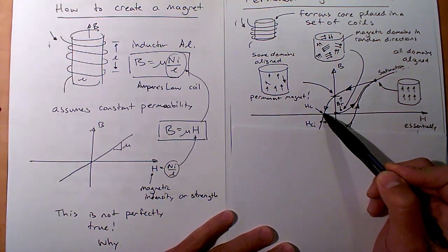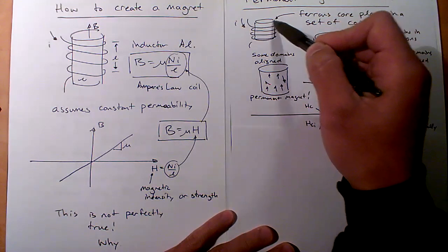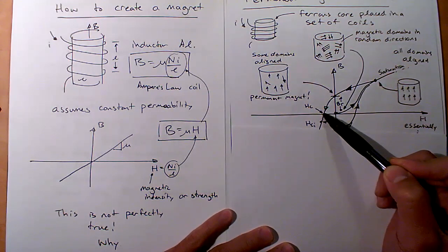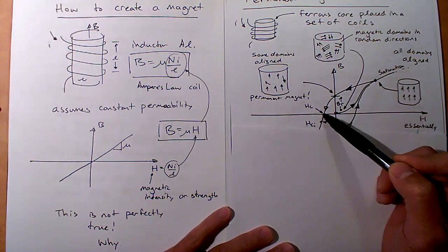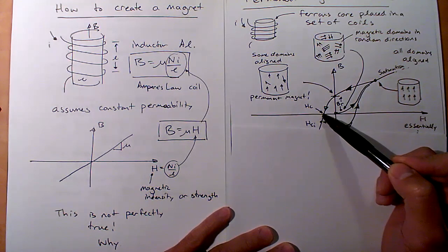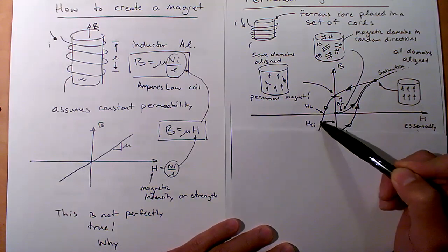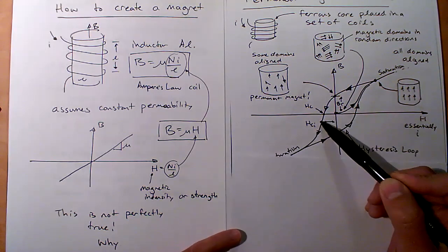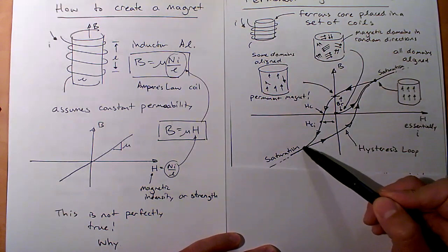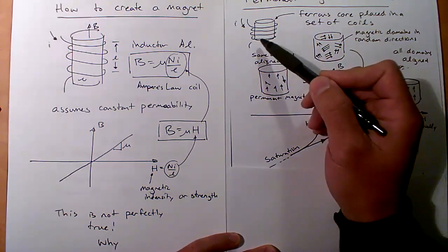This is where the combination of the permanent magnet that you created and the external intensity cancel out to 0. Okay, if you pulled it out here, you haven't necessarily demagnetized your magnet, right? It might bounce back to here. However, if you keep going to this point, HCI, the intrinsic coercivity, that will kill your magnet. If you keep going further, more negative, you would actually magnetize it in the opposite direction. So what was the north on this side now becomes the north on the other side.